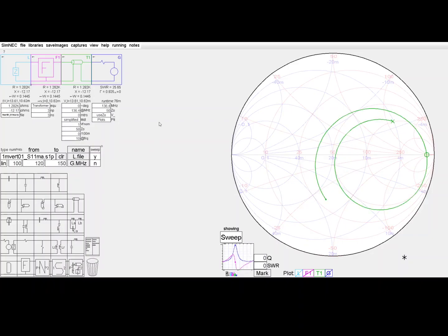So let's return to the wide frequency sweep of our test antenna. This was from 60 megs up to about 220 megs, and we'll focus this time on the high impedance resonance over here. And I've put the frequency in there as 136.4 by locating that zero crossing.